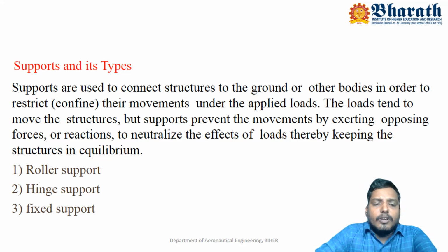Then the hinged support offers two reactive forces. It restricts the movement of the structure in two directions, but it allows free rotation. Therefore, the degree of freedom for a hinged support is 1. A fixed support offers two reactive forces as well as one moment. Therefore, translation in two directions as well as rotation is restricted, so the fixed support has 0 degrees of freedom.